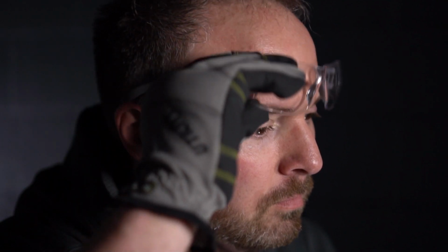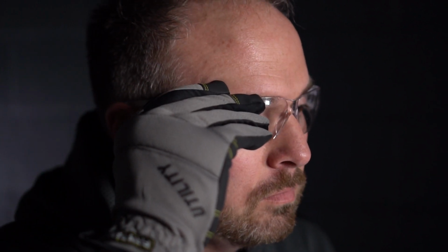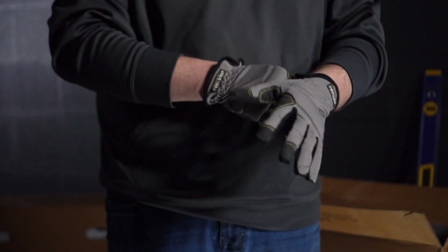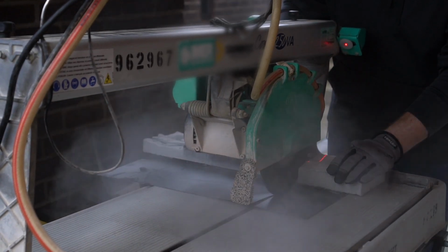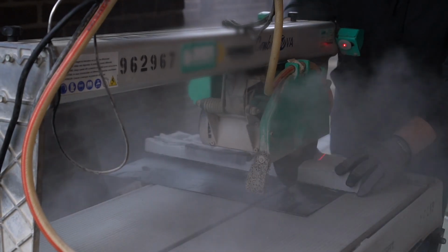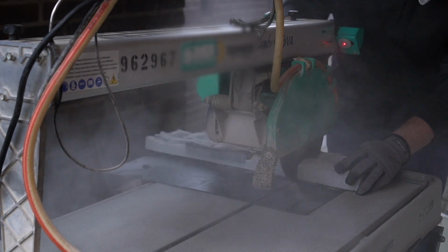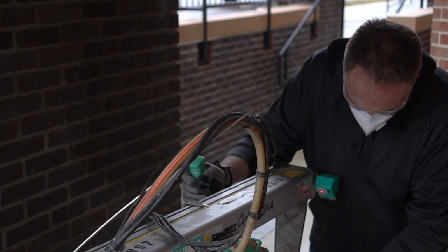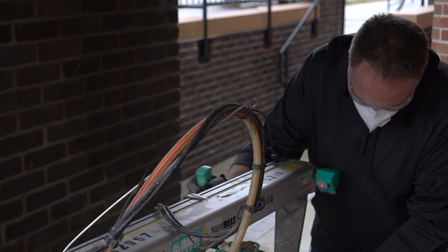When cutting panels to fit on the wall, please use proper care and employ necessary safety measures when working with and cutting Silvermine Stone. Silvermine Stone is a concrete-based product. Concrete products contain crystalline silica, and when cut, the silica dust may become airborne. Care should be taken to wear proper personal protective equipment, such as a properly fitted N95 mask, in addition to safety glasses and earplugs.